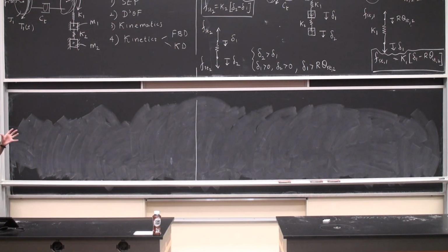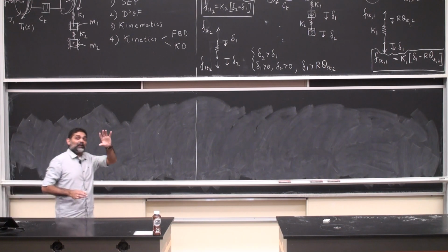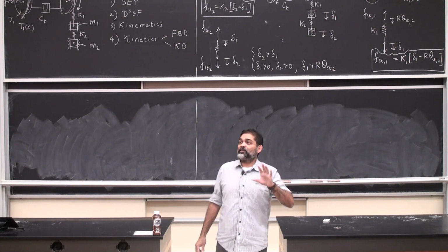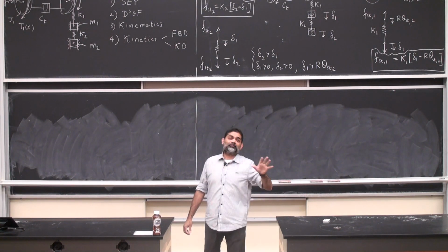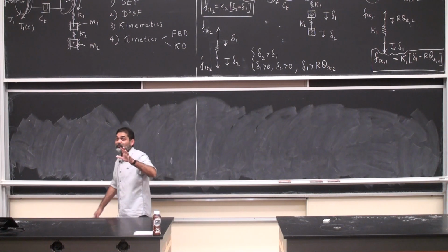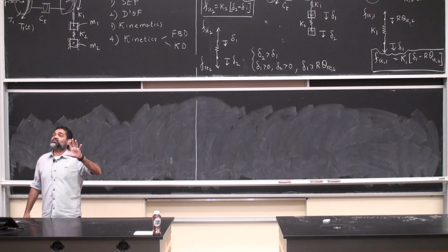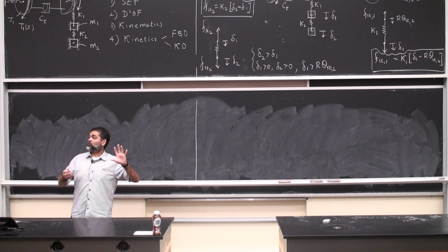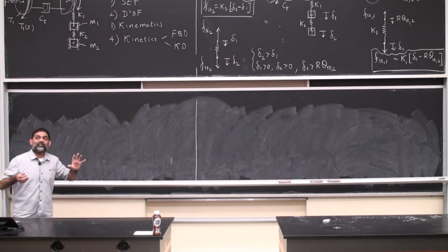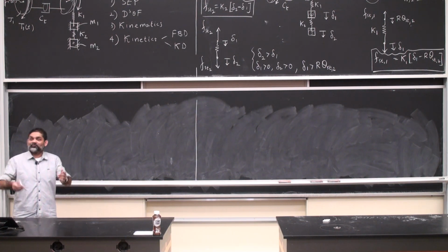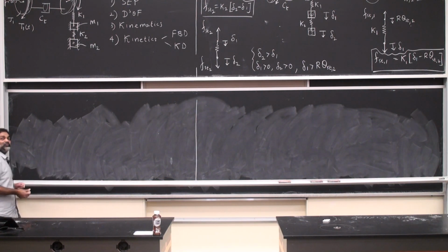Then I look at these springs. The damping elements, do I need to worry about damping elements in SCP? I don't need to, because they don't have any restoring force, they don't have any restoring torque, for all the reasons that we have discussed in the past. Damping elements only exert a restoring force or a torque for a velocity, not for a static displacement. Static displacement, if you differentiate with respect to time, is 0. There is no static velocity. It's an oxymoron.